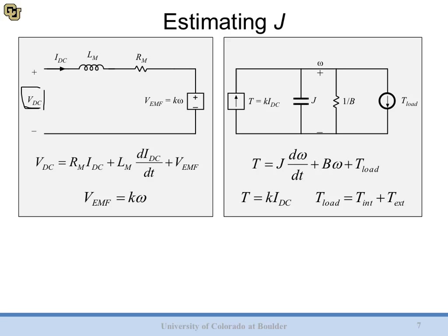Now, a turn-on transient is a little bit tricky, and this is mostly because we don't know exactly how these voltage supplies are going to turn on. If you've measured transient turn-ons with your voltage supply before, you know it doesn't just jump up to whatever voltage you set it to. There's some ramp up and some slow dynamics, and we really don't want to have to deal with that. So we're going to do a turn-off transient.